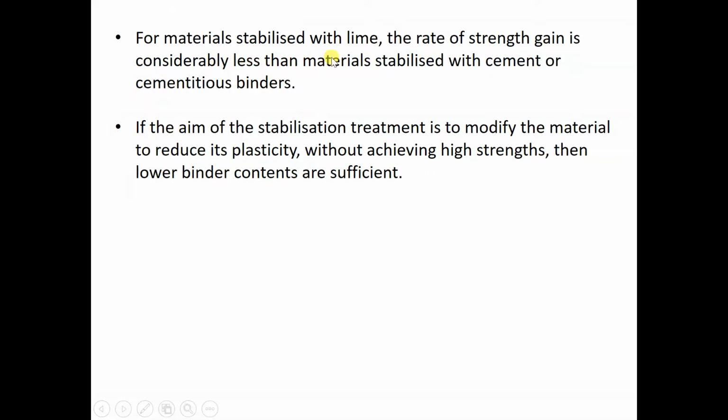For materials stabilized with lime, the rate of strength gain is considerably less than for material stabilized with cement or cementitious binder. For strength, lime will not be as good as cement or cementitious binder, or even the bitumen binder.